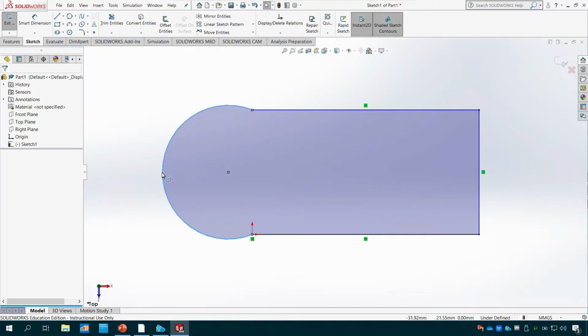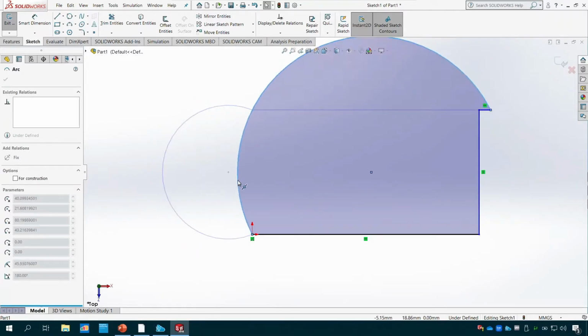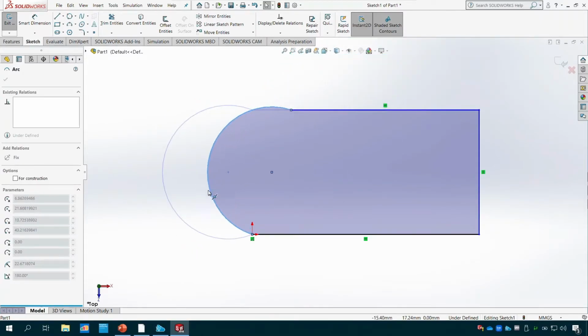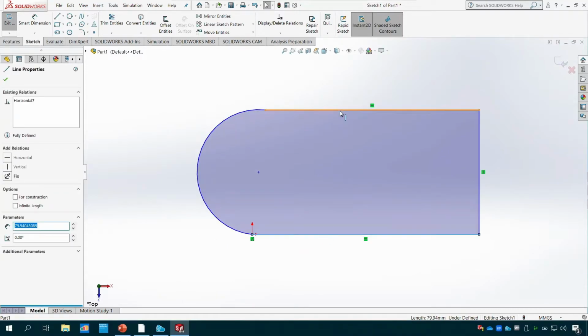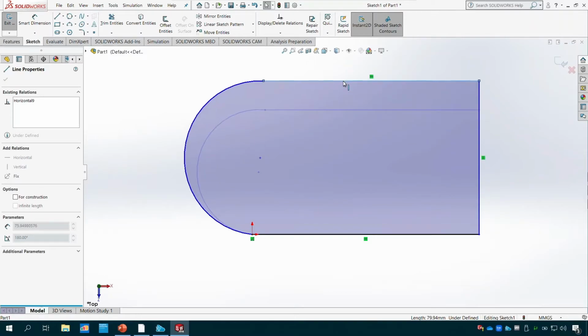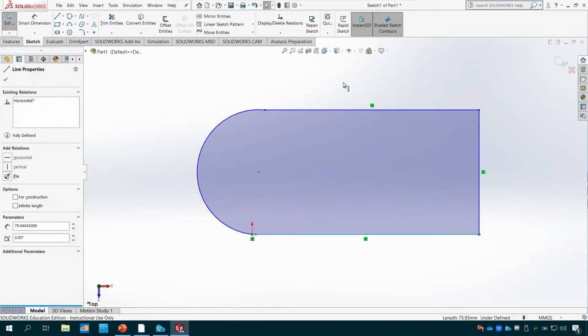And if I click on here, you will see that you have control of the shapes. The reason is that I haven't provided any dimension, and that's why the model doesn't have any constraint. I can move them around in whatever direction I want. To prevent that, you apply the appropriate dimensions and relations. So that was it for the arcs.